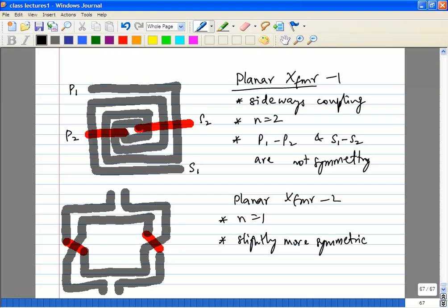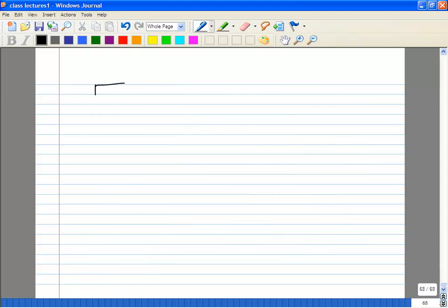If you look at the side view, you'll have very good magnetic coupling here, right? But as you go farther away, between the current flowing on the other ends of the inductor, you'll have lower K. So there is a certain maximum you can get. It typically will be 0.8, 0.85, around that much.